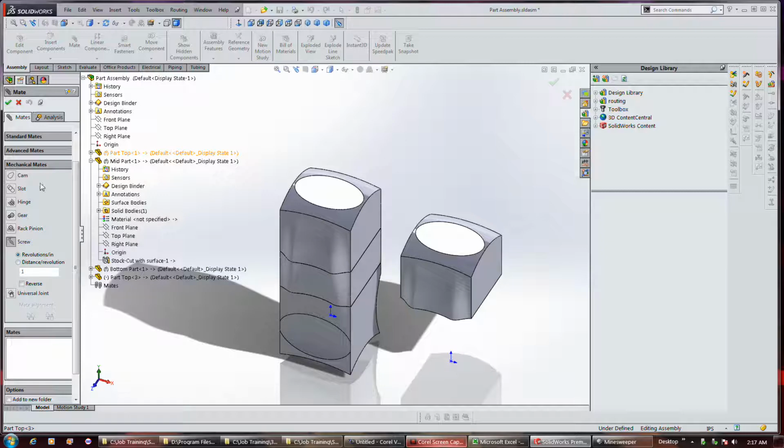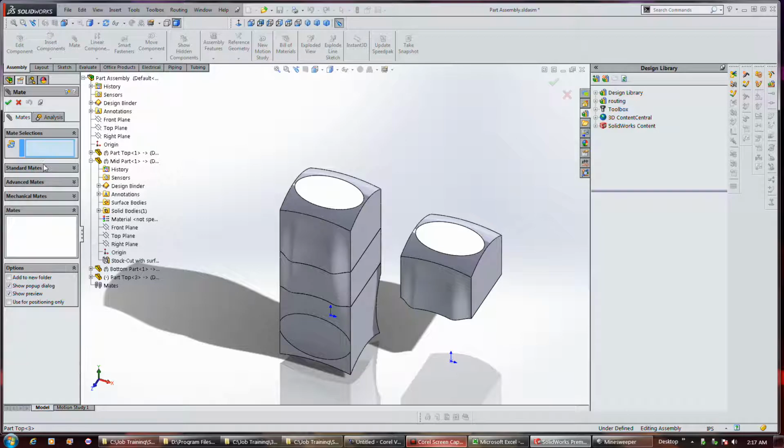Now the gears may be difficult to simulate. You may need to use the gear mate. I don't know if this would actually properly simulate a bunch of actual gears meshing or not. But the point is that's what these advanced mates mostly do, if they are creating mock-ups, a substitute for actually going in and defining all the mates, mostly for presentations and things like that.